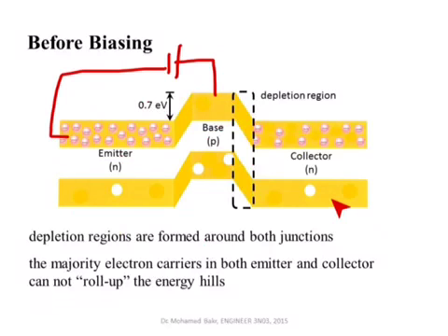Now, if we reverse bias this one, not forward bias, then we connect a battery that looks something like this. So we are making the N-type material more positive than the P-type material. Then we'll actually push this energy level even lower.